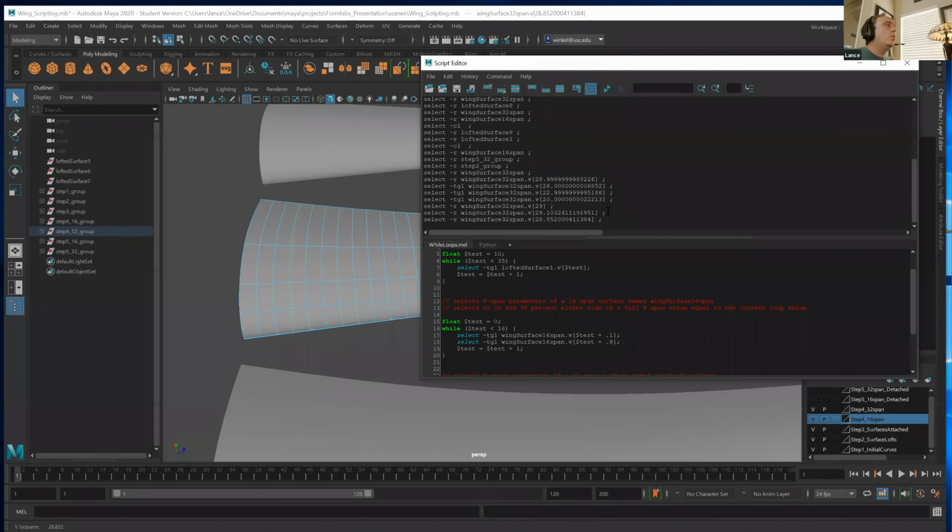Now, classically, what we could do here is press Control-C to copy that little bit of command. I can come down into my MEL command line editor at the bottom, type it out, and get rid of all of the little trash numbers I didn't need. When I hit enter, notice how it shuffles back, but it actually grabbed exactly 29 and 10%. Now I could do something like a detachment there to break it up right at that point, or some other operation based off of that curve. But what if I wanted to have the other one that's just a little bit beyond it, at that 28.9?